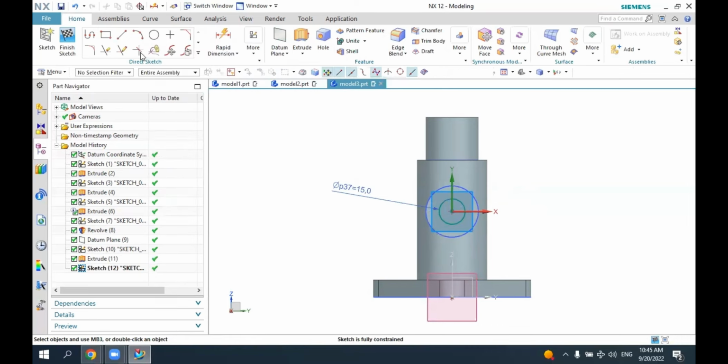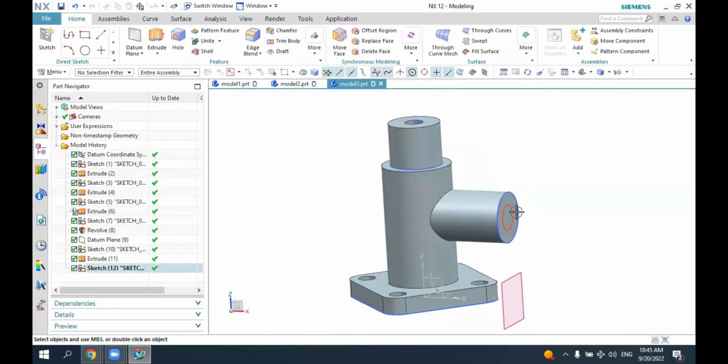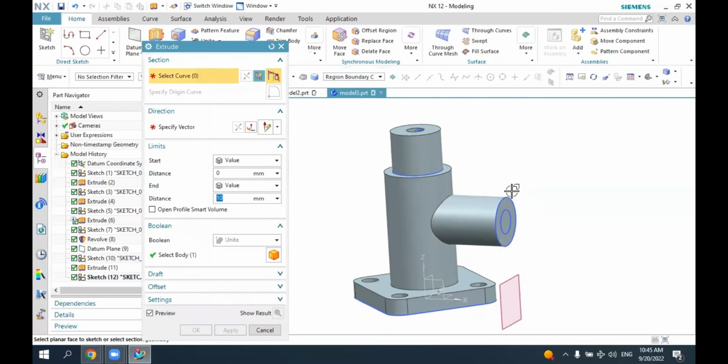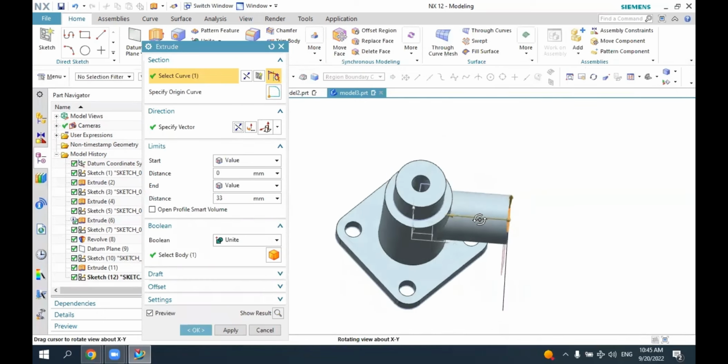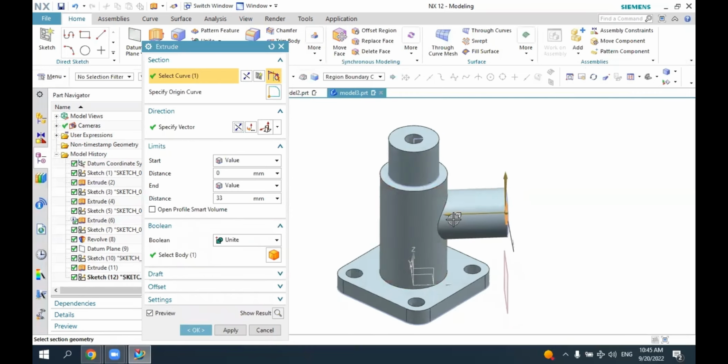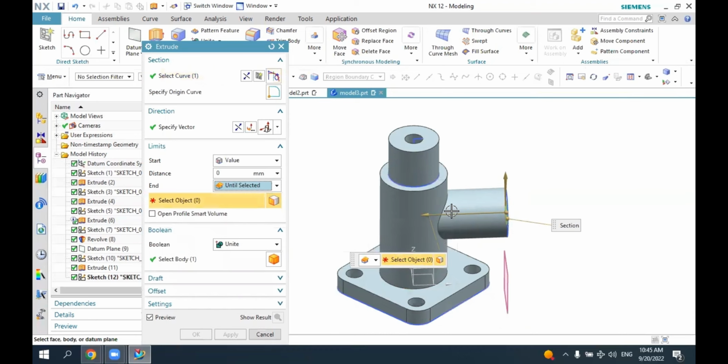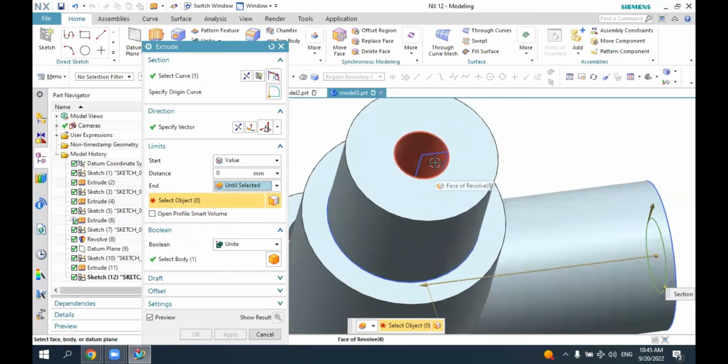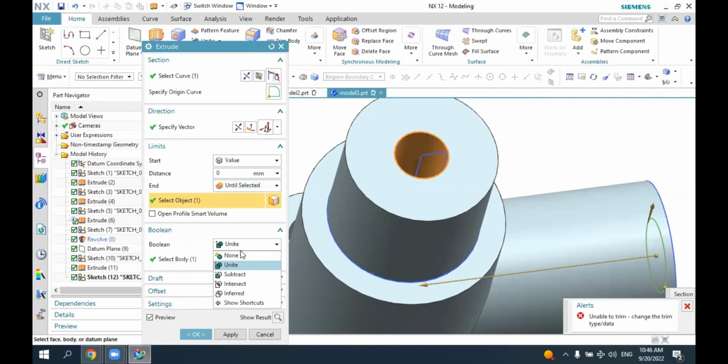Press enter. Finish sketch. So you see we created the hole, that's a circle on the datum plane. Now we can extrude it again. Select this one and reverse the direction. You can just reverse from here, but I want to extrude it and make it a cut until here. You can drag it here, or you can define some value, for example, until the selected. In this case, until the selected, you see select the inner face, but it does not work. I think that make it subtract.